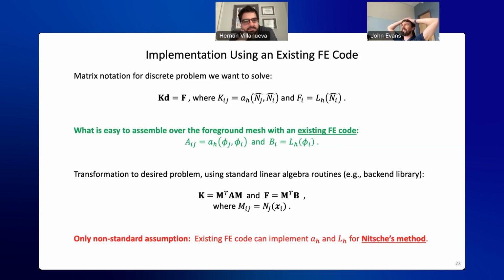And that's of the implicit representation. So you need to make some approximations if you're going to try to use level sets for representing a B-rep. So if you're going to want to handle a B-rep directly, it is my recommendation, don't go implicit.